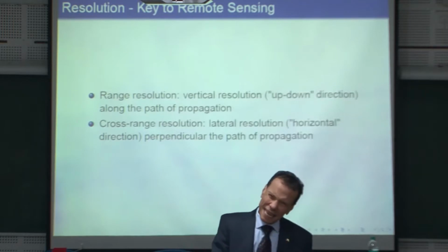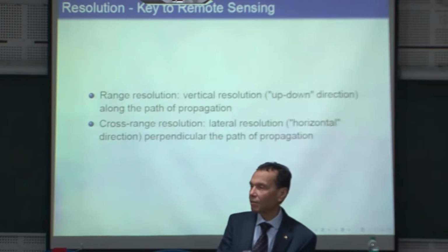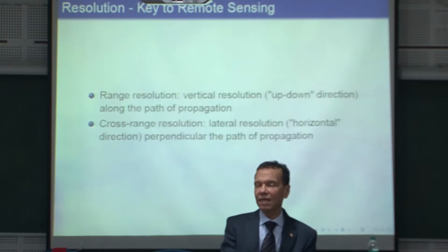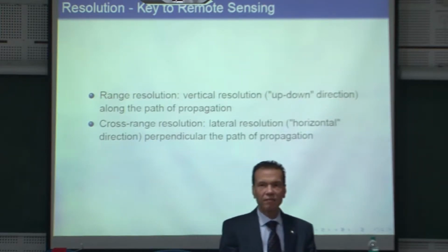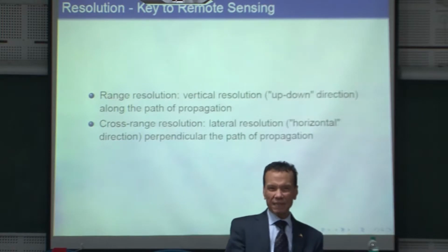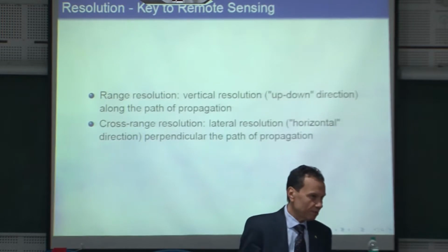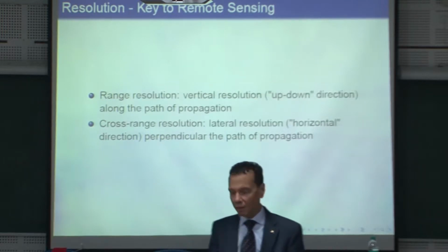Or if it is not exactly the same, at least you have damped it or made the difference as small as the others. And you can use what is called time windowing, because if you look at the data along the time domain, you see the first reflection comes here, and the other reflections come later. It is not the windowing we talked about before in the antenna and so on. It is windowing in allocating or assigning different measurements to different objects.